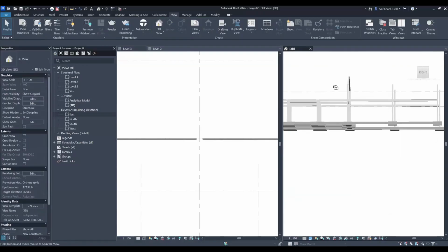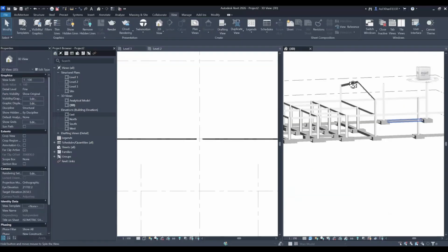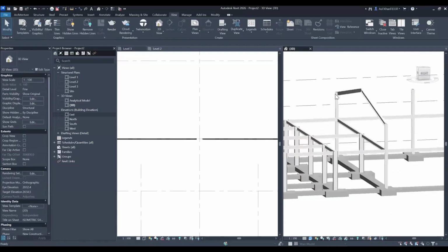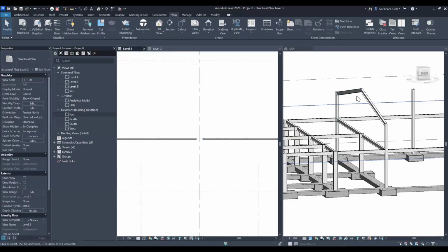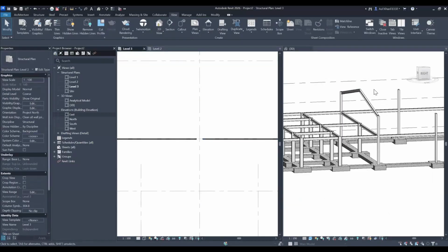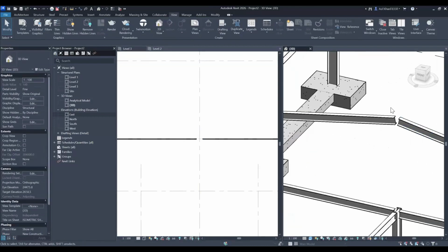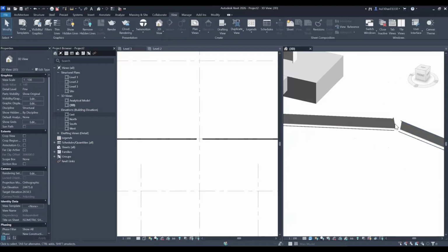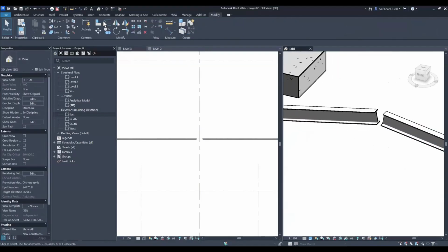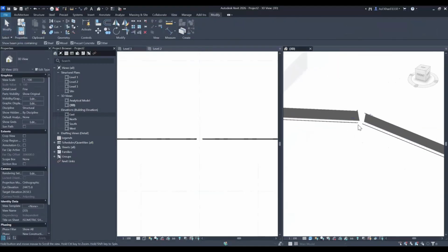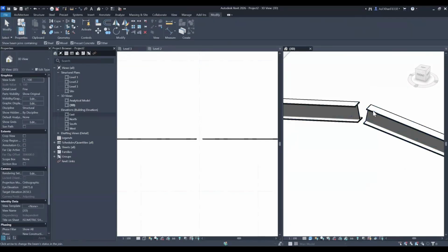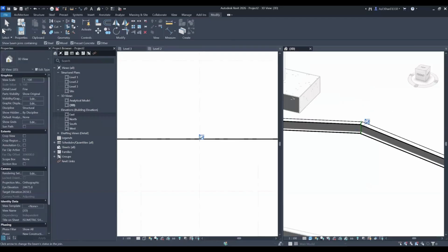I have made an industrial kind of portal frame over here just by drawing some beams, splitting them up, and then manipulating the end. The job's done. Now, if you're not happy about the connection, we have a dedicated connection tool over here, which is a topic for another day. I'm not going too deep on this. I'm going to the modify panel and clicking on beam column connection. As you can see, there are 2 arrows here. I'll just push it to the other side. My mitre connection is done.